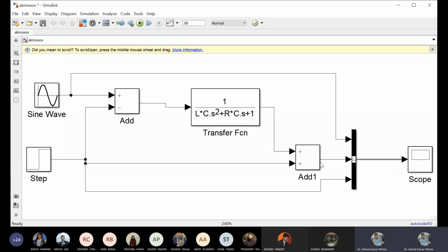then we can get here, in fact, the transient tower voltage. Why I have used this also is just to see all three plots in the same graph. What I want to show you in this curve is the varying input condition. That means sometimes the switching may be at 0 and sometimes at the peak, and the trap charge may be no trap charge, or maximum positive or maximum negative.